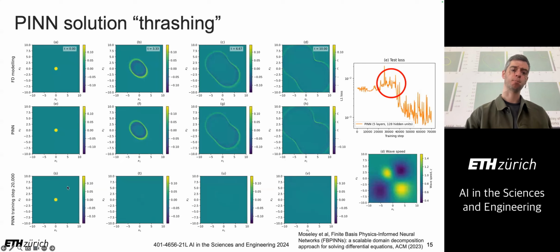And so it's interesting to plot the PINN's prediction of the solution at training step 20,000. So this is here before it started converging. And what you can see is it's learned the boundary condition well, but then the rest of the domain, it's basically set the solution to 0. So anyone got any ideas why this is 0 here? Why it hasn't even started putting amplitudes in?